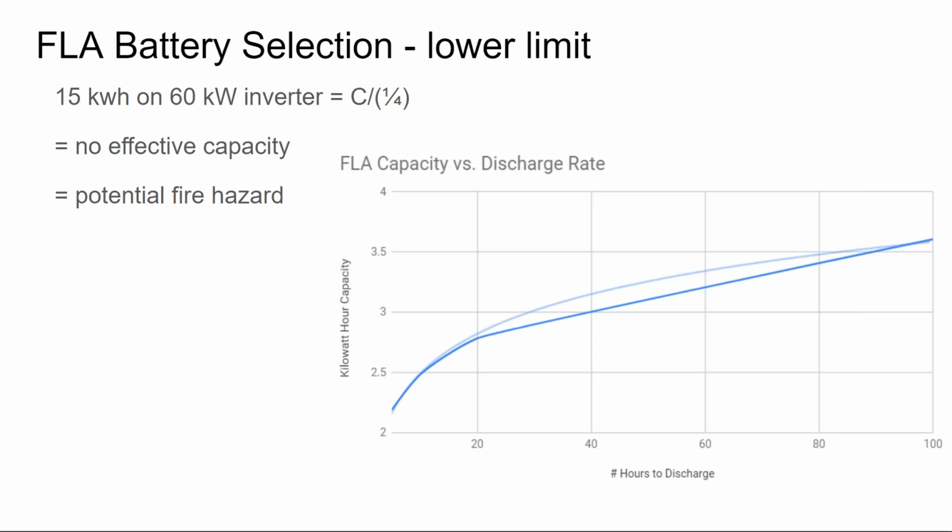When I was younger, I bought a battery and an inverter, and I thought, oh, I could power a boat lift with this thing. But the wattage of the boat lift was such that it would drain my battery in a 15-minute time frame. My battery was not large enough, and so as soon as you'd flick the switch, the voltage in the battery would drop down, and nothing would happen. The boat lift would not work.